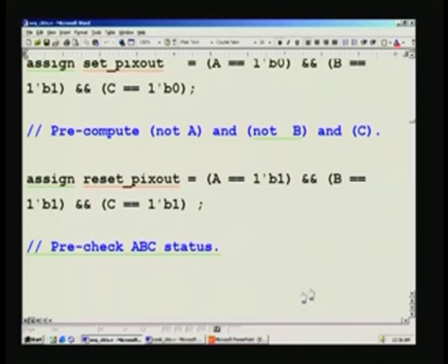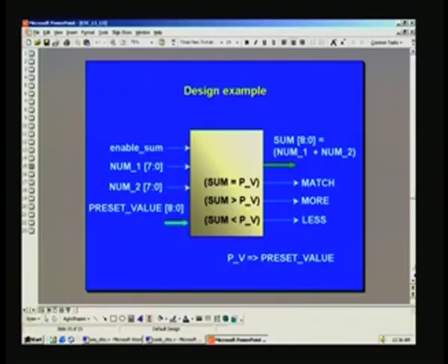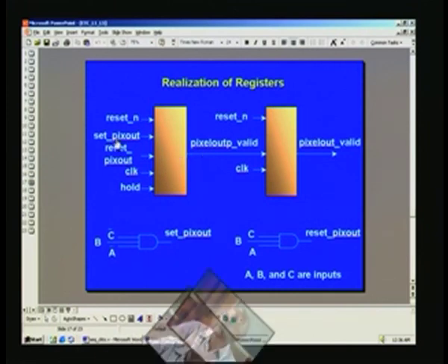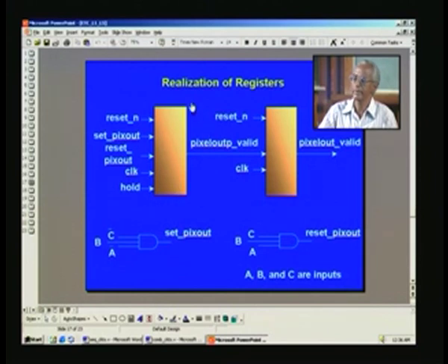And here what we have, two registers we realized in this fashion. When you have just a plain register, which is nothing but a collection of flip flops, say D flip flops, depending upon how many bits you want, and there are reset, set controls, clock and hold for this, whatever it stores here, we want to use only with the arrival of the next clock edge.